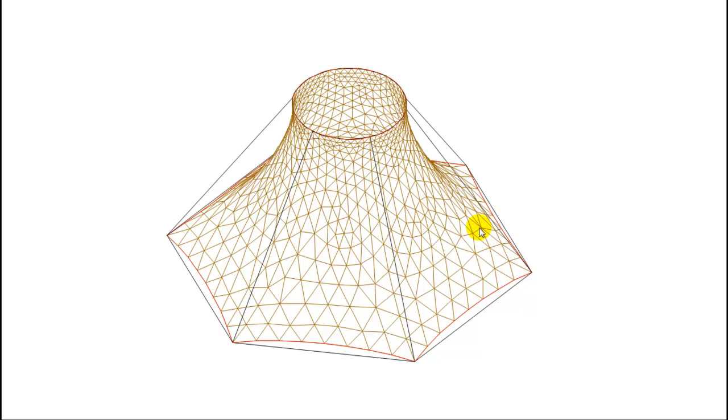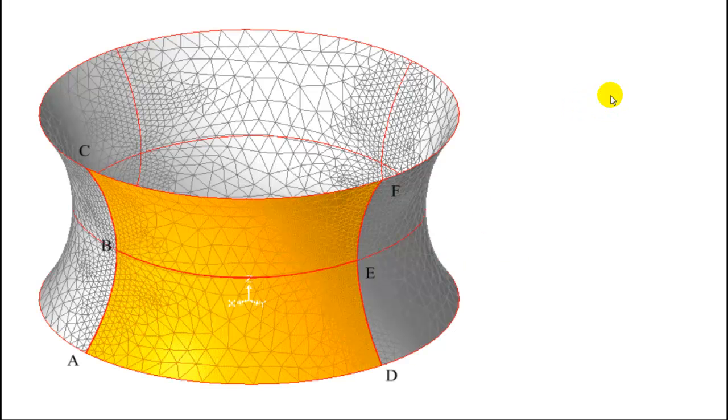The fabric cloth of a tensile structure obviously needs to be attached to the supporting structures or hull. Therefore, the proper kinematic boundary conditions should correspond to each edge and each vertex of the frame object. There are two principal approaches here. A continuous fixed edge, for example, the circle, or a scalloped edge with attachment points just at the corners. The scalloped edge incorporates a fabric pocket through which a supporting cable is run. The assumption mentioned above results in three types of edge boundary constraints.